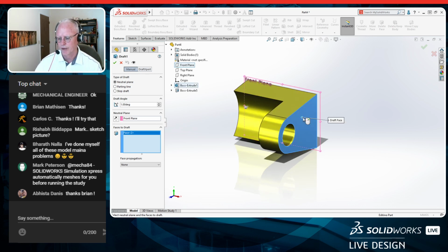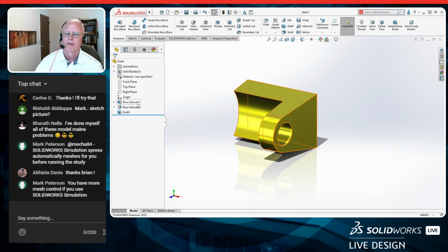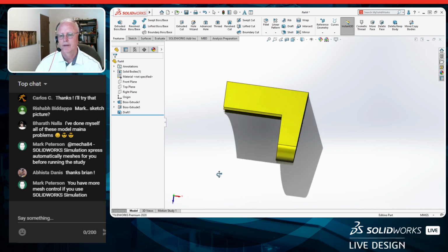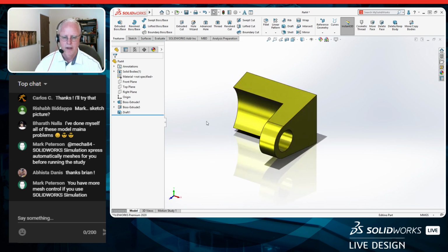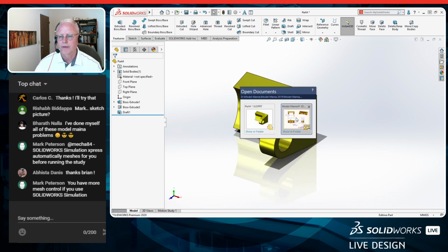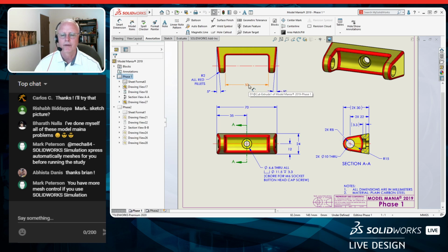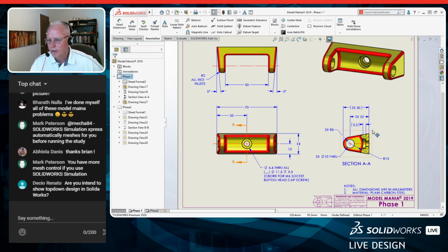I want to draft this face 5 degrees. So that drafts that face in. That looks about right. So let's go back to our drawing and see what we've got. We've got our 5-degree draft, we've got our 50 in there, 70. We still didn't put our hole in there, but that's okay, we'll get to that. All this stuff here is done with the exception of the fillet. So let's go ahead and put in this counterbore hole. Notice there's a reference dimension over here, 3.3.